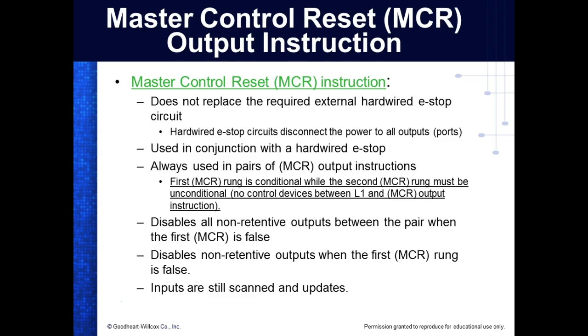So that way, if something happens to the power on your PLC, because if I'm going to hit a master reset, I'm going to kill all my outputs on my PLC. That's what I want to do. I want to kill all the outputs. But if I've got something external that is desperate like that, then we won't use the PLC, we'll use a latch and relay. We could use the PLC to latch it, and we can use the PLC to unlatch it, but when I kill power to my PLC, I'll kill those outputs, right?